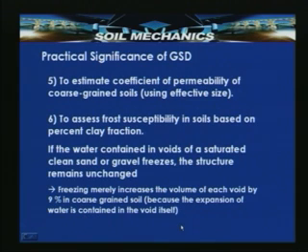The expansion of water is contained within the void itself. So, because of that they are not more susceptible, whereas in the case of fine grained soils the water which is prevalent in the voids increases, and it causes heave, which in the case of clay soils is called frost heave, because of this particular nature. So, to assess the frost susceptibility of a given fine grained soil, we are required to determine the percentage clay fraction. By assessing that, we can find out how frost susceptible the soil is.